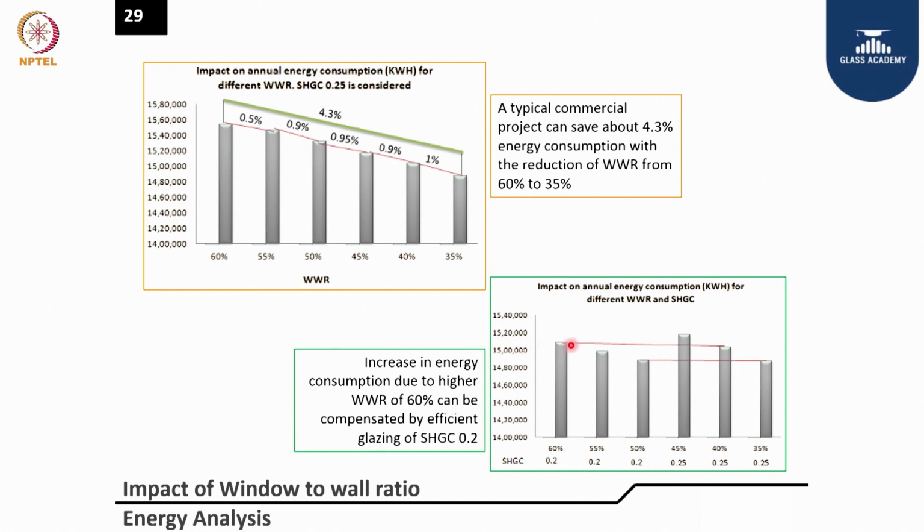You set the tone for energy consumption. It can be 90 EPI, or energy performance index. It can be 90, it can be 120. So the moment you have that number, then you can play with the window to wall ratio and glass specification and look at how to optimize your overall energy and also the initial investment.